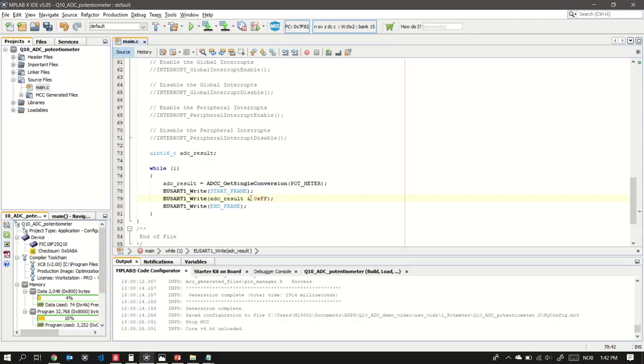And what this does is that the 2 top bits, because we have 10 bits, will be ANDed with zeros, while all the bottom bits will be ANDed with this full byte right here. So all of the bottom ones will be sent, while the top 2 will be 0, so they will not be transmitted.